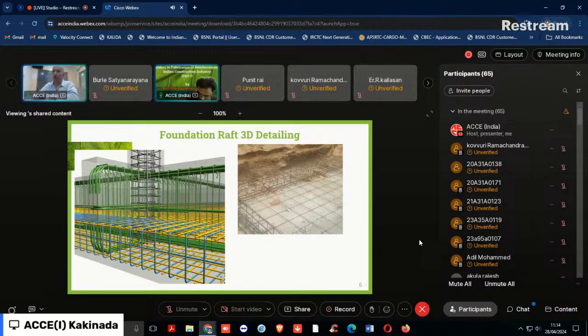And also we can see how he maintained the mandrel diameter, how perfectly he formed the mandrel diameter. We can see for the stirrups also how he used the correct mandrel diameter. This is very important from the TMT bar point of view, and also for the bend test requirements of four times the bar diameter as per IS 456:2000 or the SP 34 requirements. Therefore, nowadays, whenever the client is interested or able to pay the subsequent cost, it is better to have rebar 3D detailing instead of 2D detailing, which gives minimum mistakes and minimum errors during the execution of rebar fabrication on site.